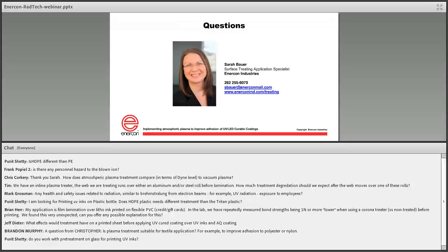Health and safety issues related to radiation. Actually, this is a good question. It came up not too long ago. When you do work with UV light, one of the really important factors is that you have some kind of guarding between your operator and the UV light, because there's radiation exposure. With these systems, unless, the best way to put it, you were staring straight up into the discharge head, there are no health or safety issues related to running it in a normal working environment.